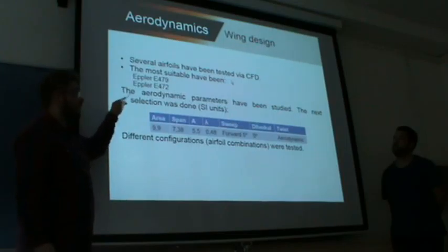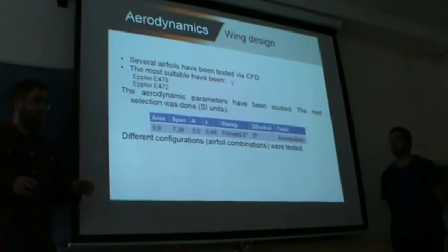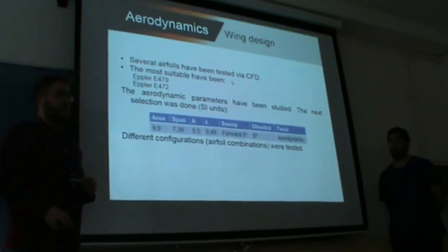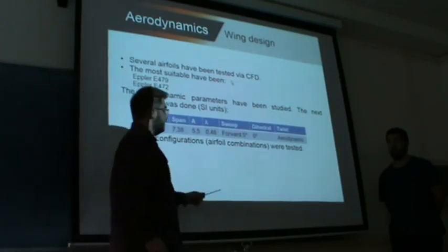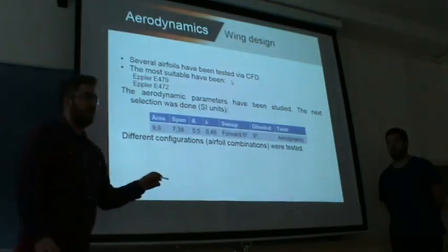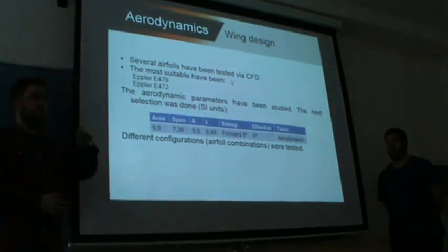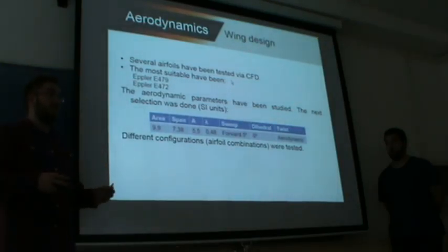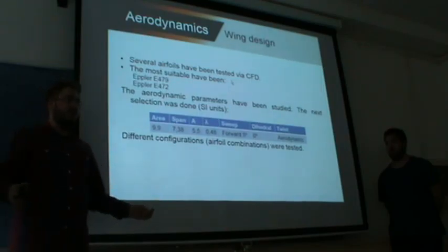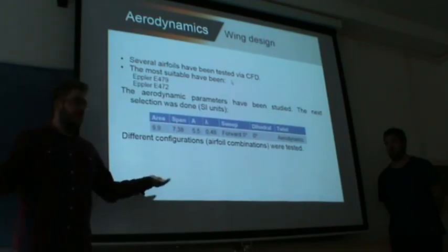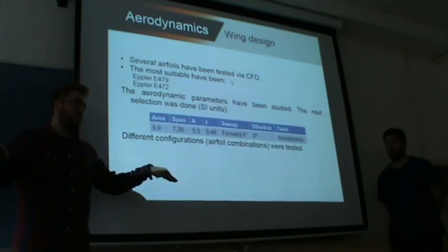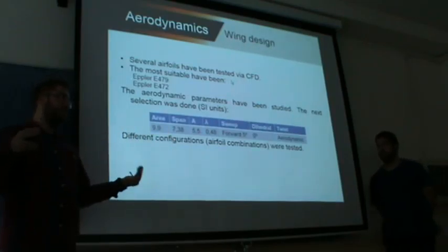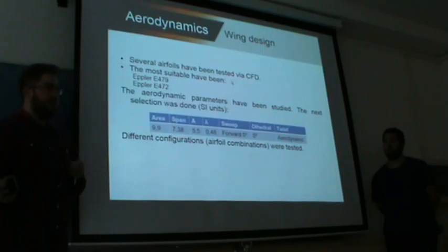After doing that, the team has also compared different types of configuration parameters and has come to the conclusion that these are the most optimal solution for our kind of wing, and we have centered on this. It's not possible to have a geometric twist because when we invert the flight, the pilot will experience negative effects. For example, if we have a positive twist in one regime of flight, when we invert the flight, these effects that were positive become negative. So we don't want this.